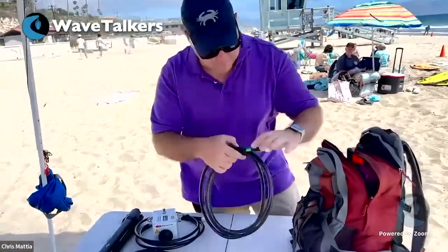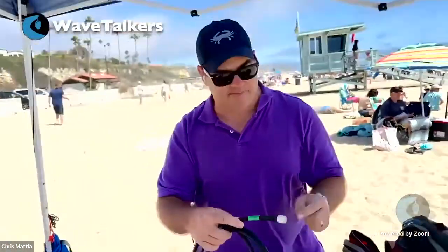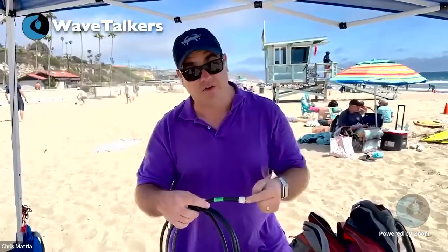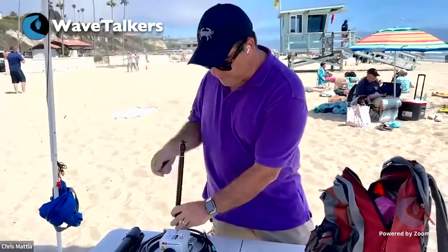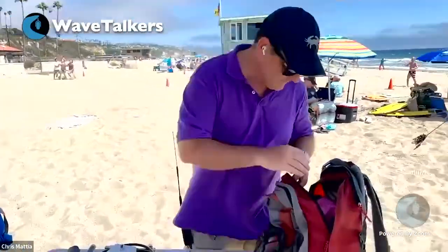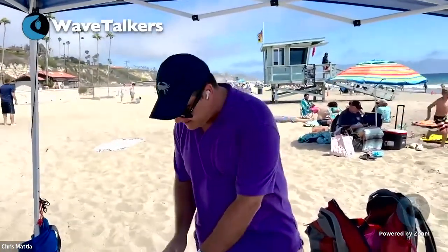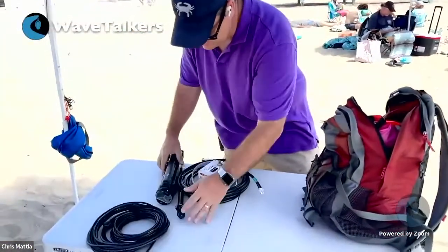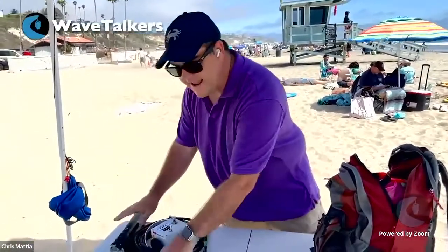It's also real important to look right on the coax. It tells you that this is shorted coax. You don't want to put this in line because the center conductor and the braid are both shorted together in these two pieces of coax, and they come with the F-Loop 3.0. That aside, I've also got, this is the center pole for the F-Loop, and this is used to hold the loop up, and the active loop, and that will go onto the top and hold the connect up. So this is an entire antenna system right here using one of the lengths of coax to connect that up. So that's one antenna. If I needed to use just that, I would be ready to operate with that.